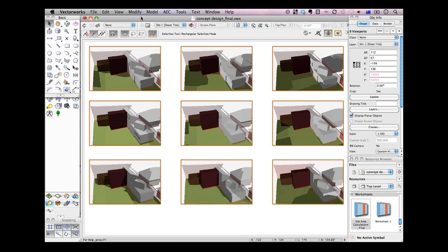Site models work with it, send to surface works with it. Send to surface will only send objects to sit on a site model, a Vectorworks site model, and that's a mathematical model created inside Vectorworks. So just bringing in 3D polygons doesn't automatically do that. But in Vectorworks you can create a site model. Unless I'm wrong, I think you can only create it from 3D loci or 3D polygons or 2D polygons converted to one of those two.